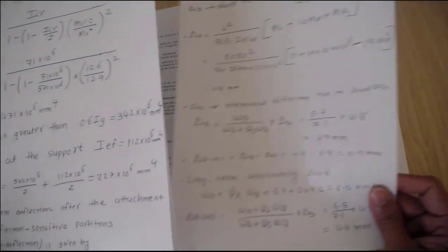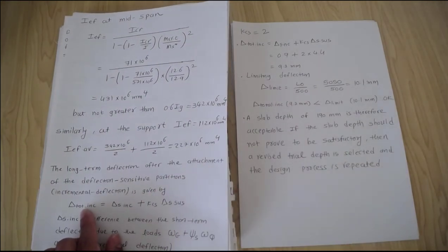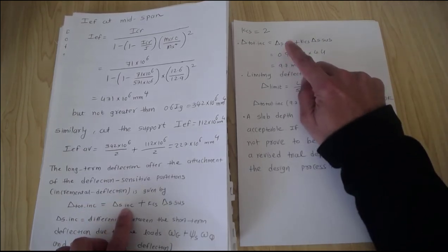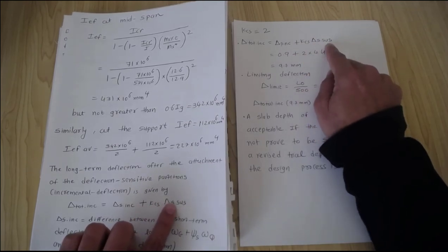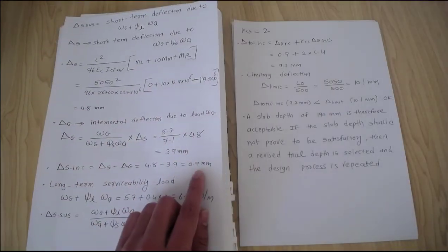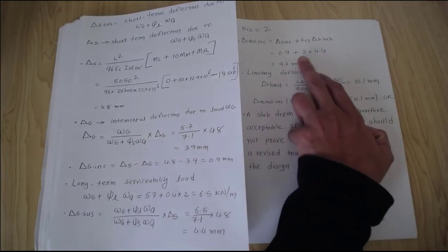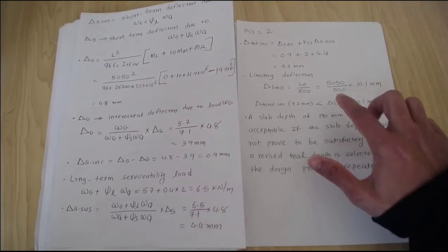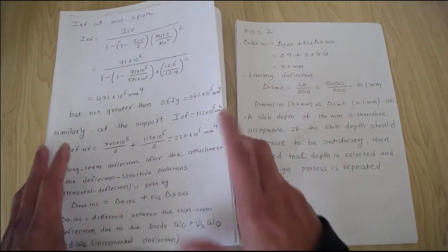Now we have all the required parameters to calculate delta total, the long-term deflection, which is the incremental short-term deflection plus the creep and shrinkage factor times the short-term deflection due to the sustained loading. So 0.9 millimeter, the incremental short-term deflection we calculated, I substitute here. KCS we just found, and this delta sustain we found as 4.4, I substitute here. So the answer is 9.7 millimeters, that is the deflection.